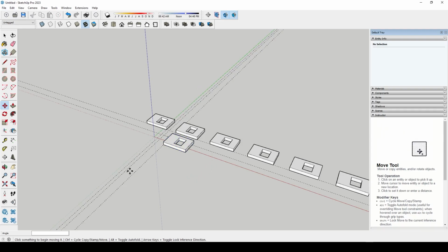Same thing if you wanted to make your own brick feature wall inside SketchUp. Let's say you've got all of the bricks sorted down here because you did the first brick and then you copied them all the way along. Then you copy them upwards and offset them so that you've got a nice running bond along there. And then all you would need to do is select all of them, go from the bottom to the top of the wall and split the difference from the amount of courses it has. And then you've got a nice feature brickwork wall there inside SketchUp. So using the copy and divide tool, which is just the / after you've done a copy, is very, very useful. Let's go ahead and clean this up a bit now.